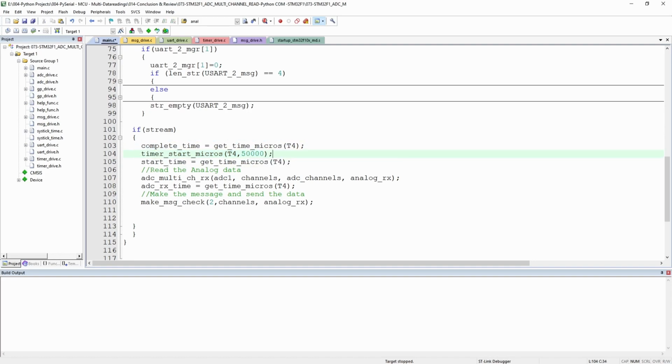We are going to use our timer library to first initialize a timer, and this timer will be 50 milliseconds, which is far more than how long the process will take. After that, we take the start time, which comes immediately after, so we know exactly the offset between these two events.